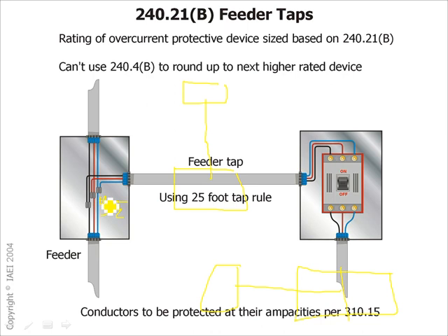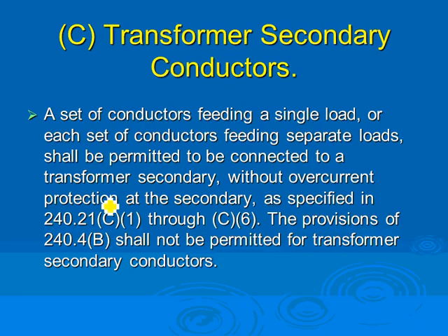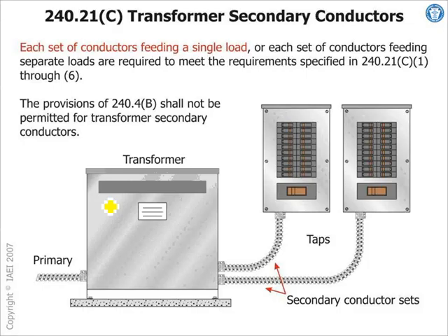Any comments, guys? Any questions about that? Tapping the taps. Yeah, industrial, 25 feet. Industrial has its own limitation though. If it's non-industrial, it has a couple of other rules. So tap, okay, 25. Okay, so let's talk about transformer taps, shall we? Transformer taps. Any questions, guys, about the 10-foot tap without transformers? Let me talk about transformer taps.